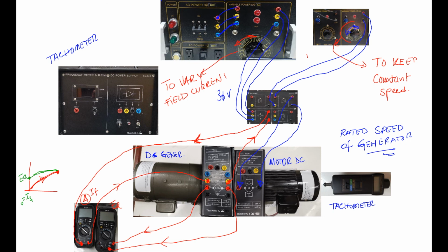Now, if you need to use this variable, this fixed tachometer, the way to connect that one, look, we have to supply it. To supply this one, we need 12 volts. So we take our red and ground here. There's this red and black.